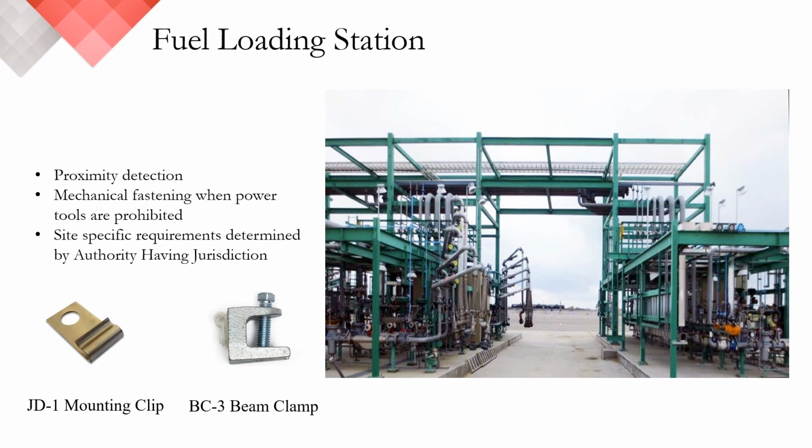I think one of the biggest installation errors I see on a regular basis is when Protectowire is zip tied directly to a pipe, and there's no flexibility for the detector to breathe. There's no slack in the installation. The detector's clamped down so tight that mechanical damage could happen. I think this is one of the types of installations that really riles me up because it happens so often.